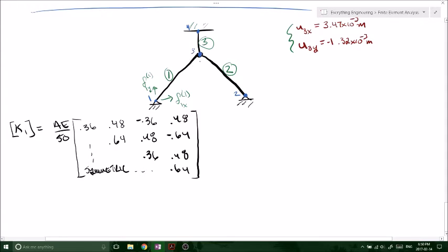Alright, so now there's also going to be, I'm just making these directions arbitrary, but we just know there's going to be an f3y due to 1 and an f3x due to 1 as well. Okay, so we can find those internal forces, and take the magnitude to get the overall member force.